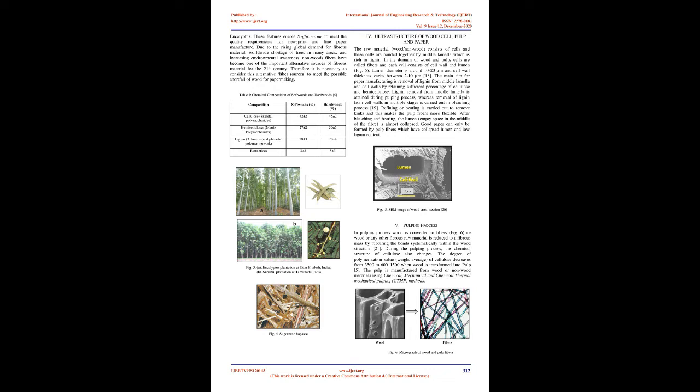10. The low molecular weight substances in wood are classified as organic and inorganic matter. The organic matter is commonly referred to as extractives and the inorganic part is summarily obtained as ash. The extractives, extraneous components comprising aromatic compounds, terpenes, aliphatic acids, and alcohols, interfere with the pulping process by causing foaming and corrosion. 11-12. The ash content of the fibrous raw materials indicates the presence of inorganics, K, Ca, Mg, and Si, in the range of 0.5 to 1% in woods.